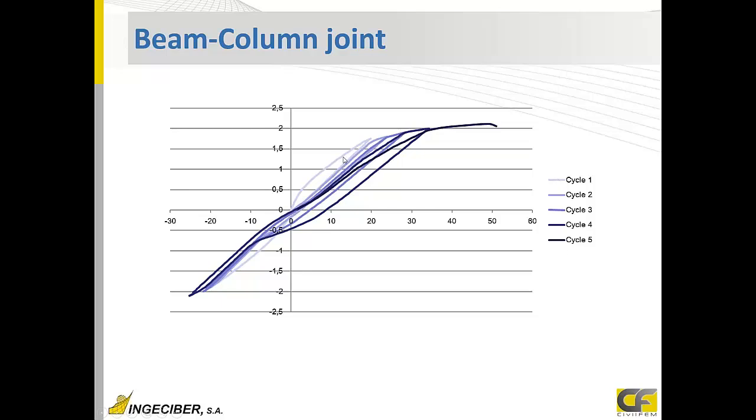Here we can see the first cycle, loading and unloading, loading with progressive damage, loading. The first one is more parabolic, due to concrete failure. And the last one is more yielding of the reinforcement, because most of the concrete has big damage. So it's more straight and bilinear, and the first one is parabolic. We can see here the last unloading, loading in the other direction, and unloading. It shows this behavior until it breaks down.